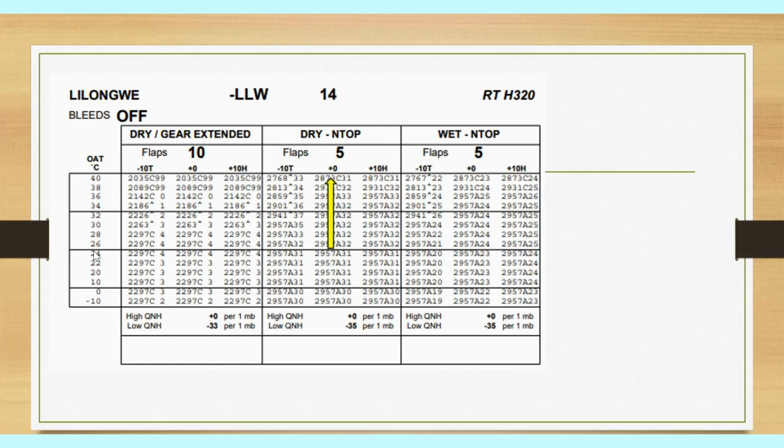You locate the outside temperature on that particular day. You find how much weight you can carry for that temperature. Then you start moving upwards along this line until you find the weight value that is closest but the highest to the actual, not this one here, but the actual load sheet figure. The load sheet figure was 27,600 kilograms.